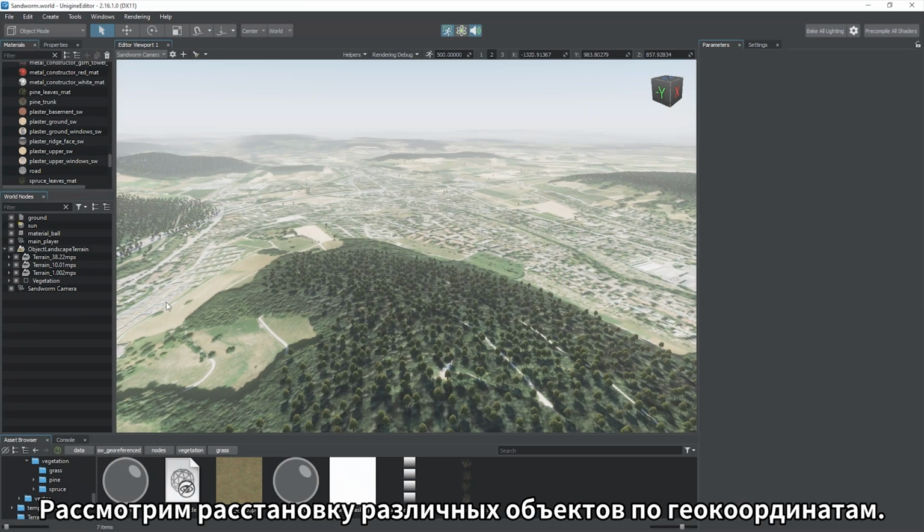In addition to roads projected onto the terrain surface, we can also place objects along splines, such as this section of a fence, or various communications like water pipes or electrical networks. When preparing a template model, take into account the position of the object's pivot point. Sections will be placed according to it. If you want a fence along the road, not in the middle of it, you need to shift the model to the side by half the width of the road.